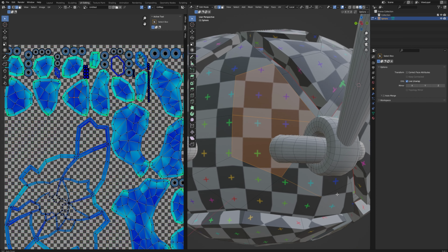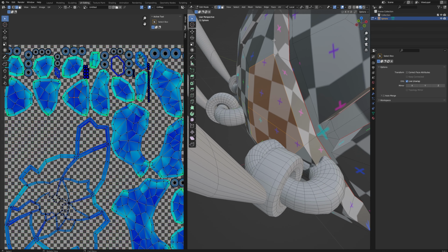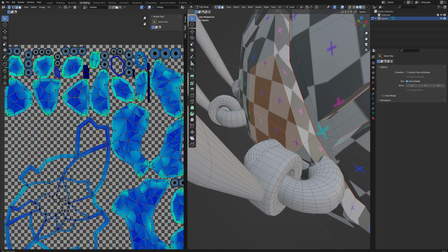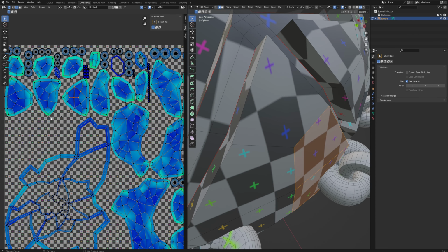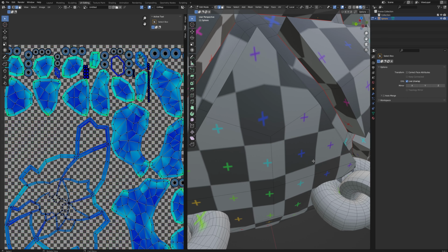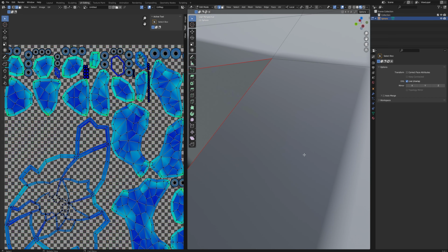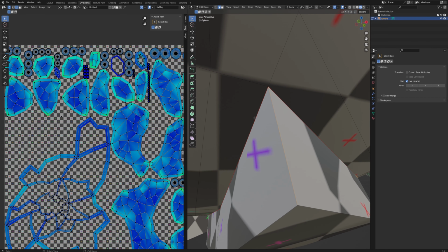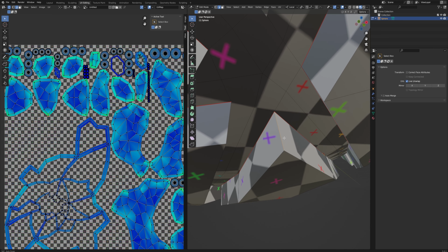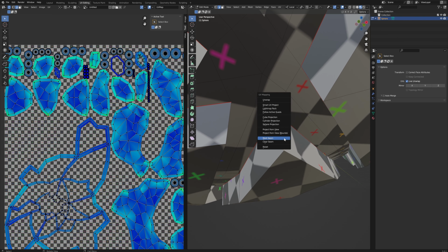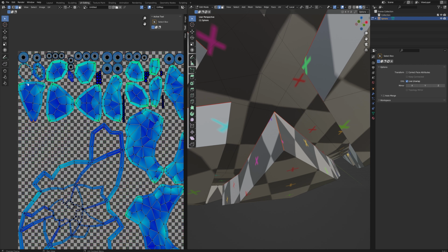So instead of making an entire go around making the top rows here all seams, which is not going to do too much in reality, what we can do is just pick the point where there is the most stretchiness over here. Then with the period key on the numpad, we can orbit around specifically those vertices, or edges in this case, and just mark that specific edge as a seam.